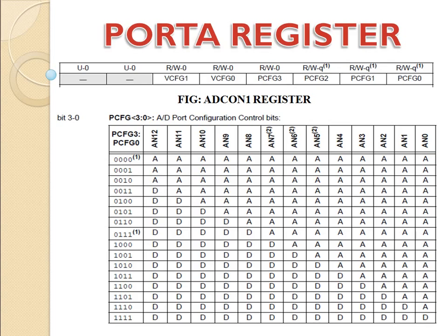Now every bit change in the value will change the pin status, like the value 0011 will make AN12 as digital and the rest as analog. The next change, 0100, will make AN12 and AN11 digital and the rest analog. This can be followed up to all ones, where all the pins from AN12 to 0 will work with digital signals.